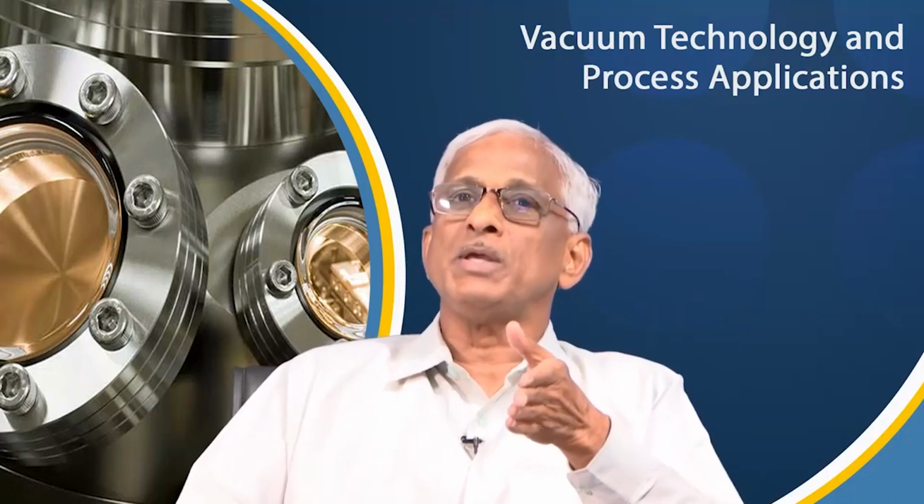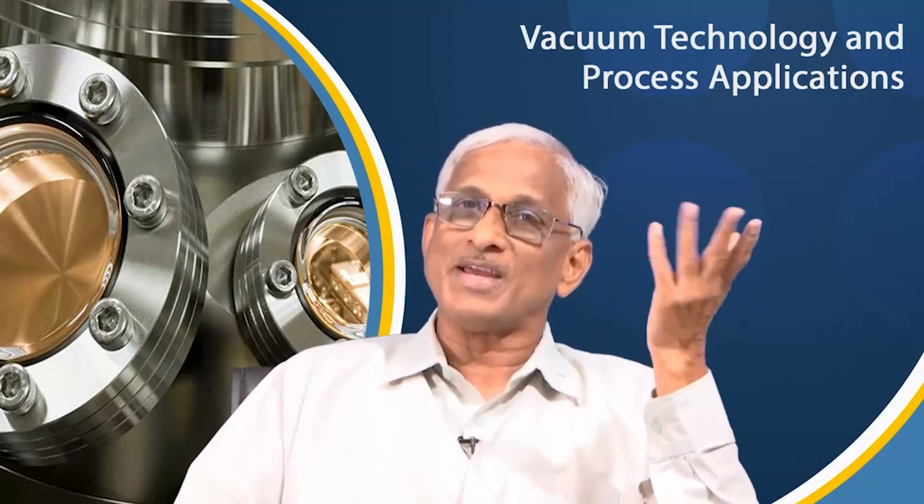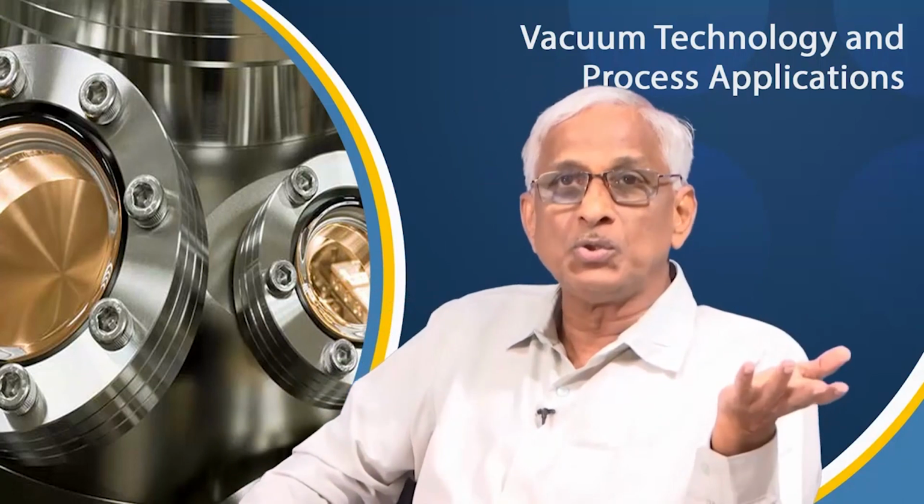Okay. Today, we will try to confine ourselves to high tech applications involving high vacuum and ultra high vacuum. In the last class, we saw low vacuum and medium vacuum. So, today our story starts from 10 power minus 3 millibar onwards. As I told you several times already, 99.999% has been removed. Where is 1000 millibar, where is 10 power minus 3? 6 orders of vacuum we have already improved, but no metallurgy application, no electronics application, no space technology application, no nuclear application, no tube applications, X-ray tubes. So, most of the high tech has not started.